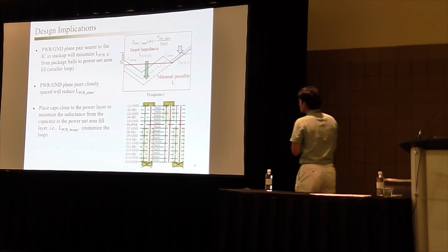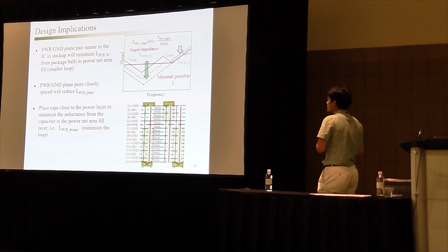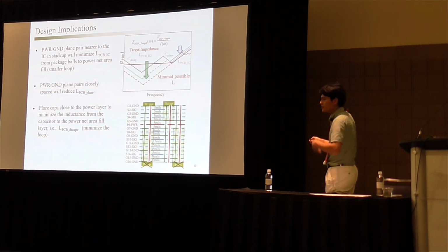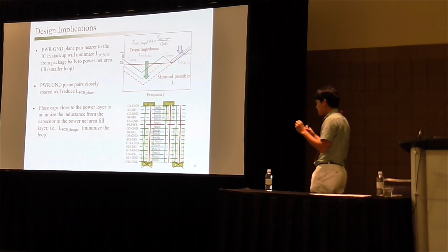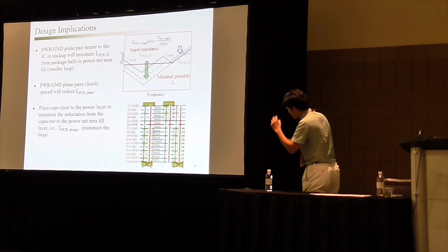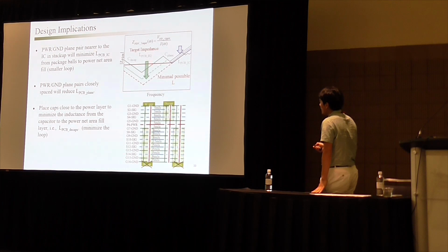So let me touch on the design guidelines for multi-layer PCB design. This is a very typical curve you may see for any complicated board. High frequency here is mainly governed by the geometry between the power ground layer and the PCB, the power ground layer and the IC. So adding decoupling capacitors doesn't help for this high frequency.